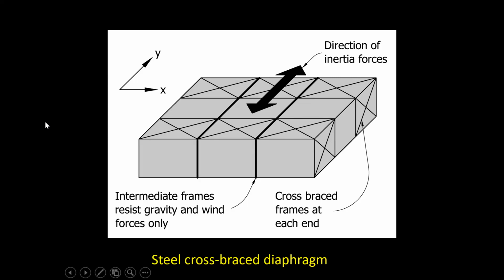So when it comes to a wide span structure, usually the roof will be rather light. Then we have to create horizontal diaphragms using like horizontal trusses. And so in this building here, we hear the earthquake forces acting in the Y direction. They are ultimately resisted by cross bracing at each end of the building, here and here.